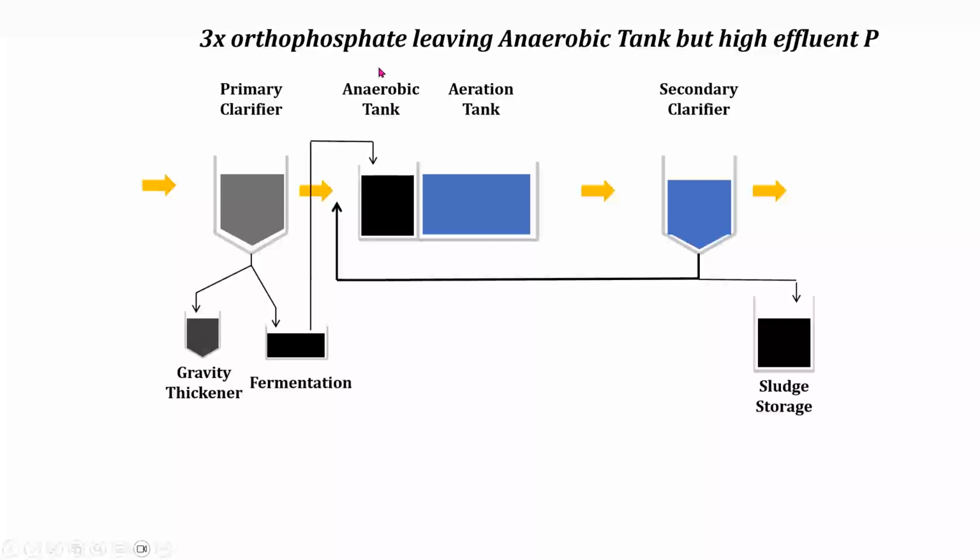So my first thing is to look at the anaerobic tank. Is it doing the two things I need it to do? Is it creating the volatile fatty acids? Frankly, I can monitor that, but I think the better tool is let's monitor the conditions or the performance.